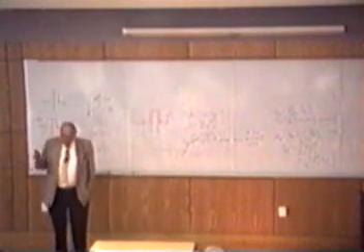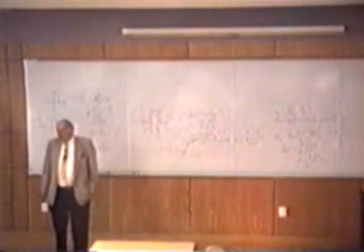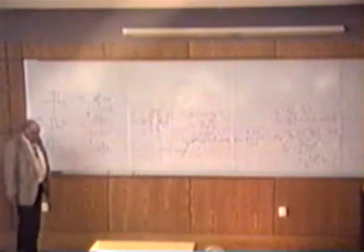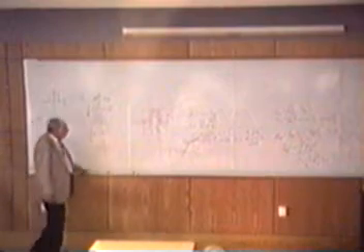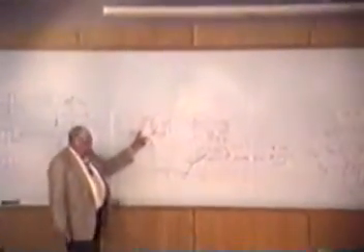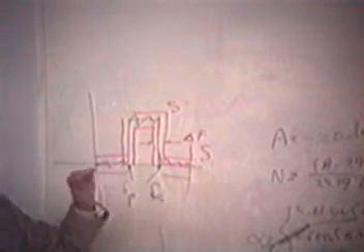What he did was a combination of theory and using a computer to get a formula. Now, Kaiser's formula works very well, except for a couple of difficulties. Once in a while, see this edge, he calculated for a single edge. There's 2 edges in a bandpass filter, and there's 2 more over here on the negative frequency, so there's really 4. The ripples induced by those sometimes work together and show a bigger error in the delta than you planned for. So what you have to do is cut the delta down in size and repeat.